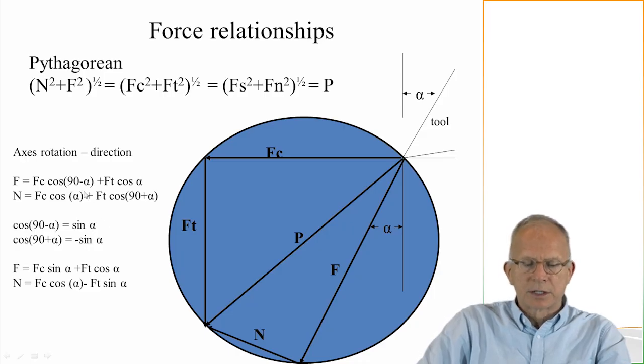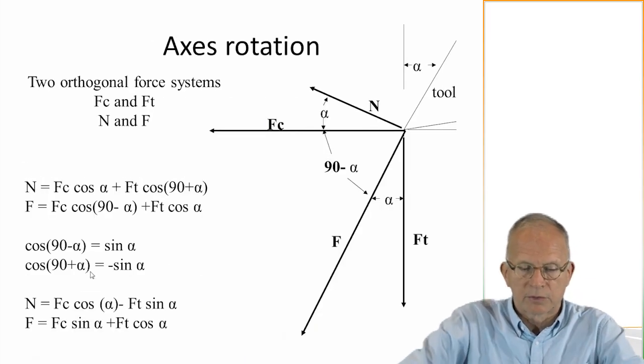So what we're doing essentially is a dot product, using the angles that you could see on the previous slide, for example, and you could work them out here. From alpha, you can see, all we're doing is moving from one coordinate system to another. And this composes what we'd call the direction cosine matrix in a coordinate transformation problem.